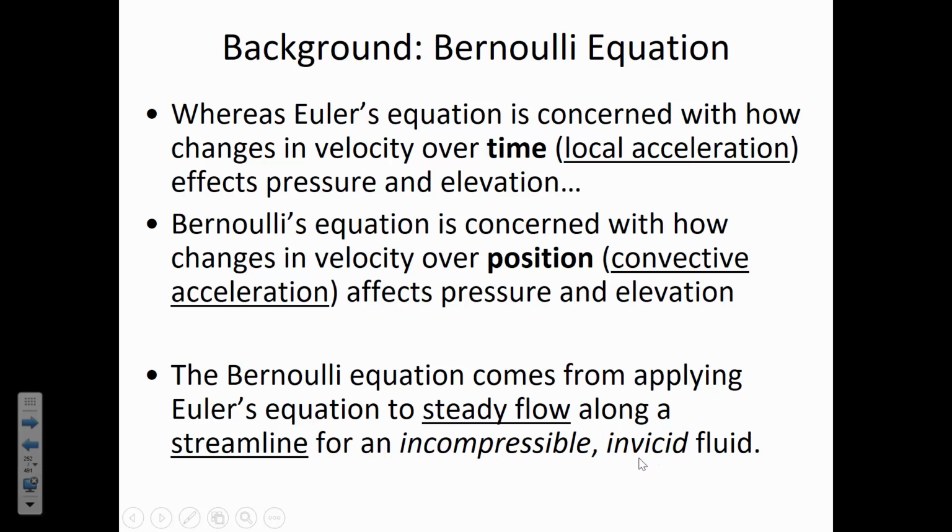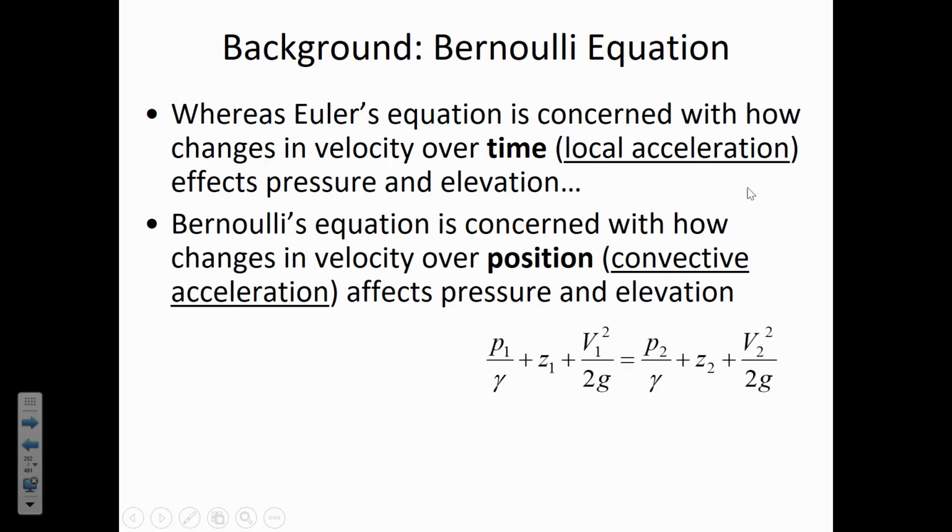Now the reason why that inviscid fluid assumption is there is that an inviscid fluid is one that's not going to experience any pressure change due to energy losses. There isn't any pipe friction for an inviscid fluid. And Bernoulli's equation, these two terms, the amount of energy at 1 and the amount of energy at 2, doesn't account for any losses between the 2 points due to pipe friction.